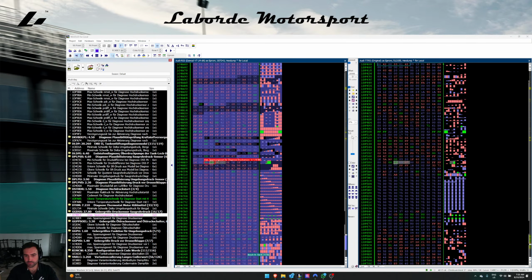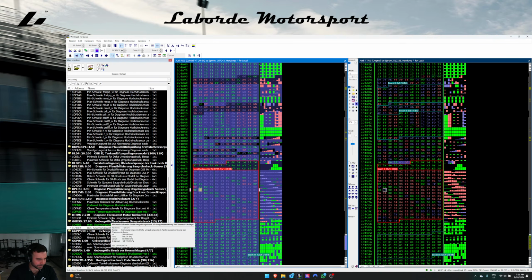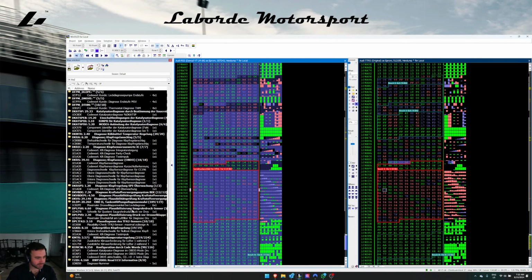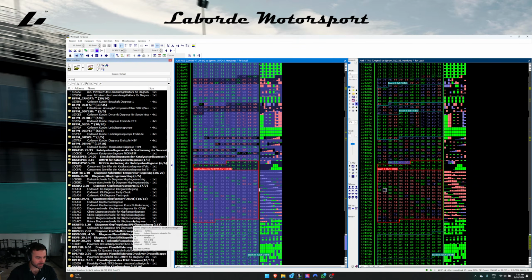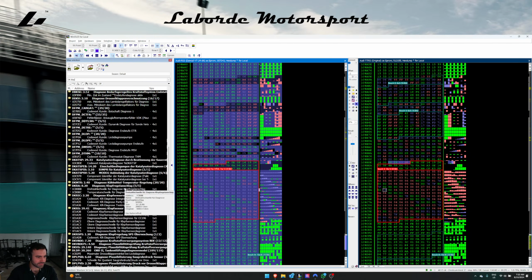Cool. That's definitely the one there. That is the ambient pressure sensor. That's the boost pressure sensor. Let's have a look. So we go DK, diag. DK is the throttle plate. Okay, Drosselklappe. That's what it stands for. Let's see if there's anything we need.